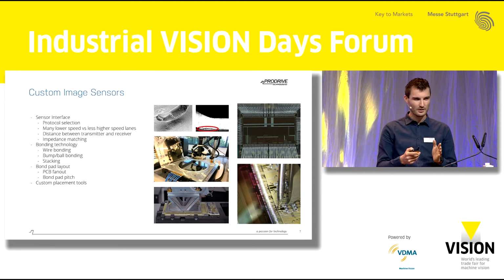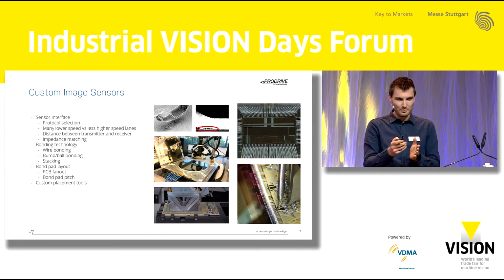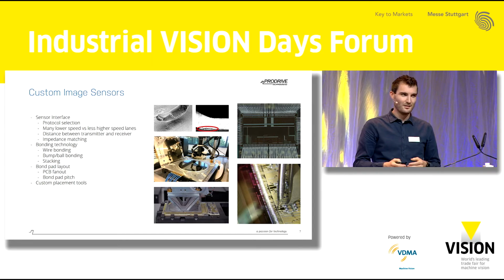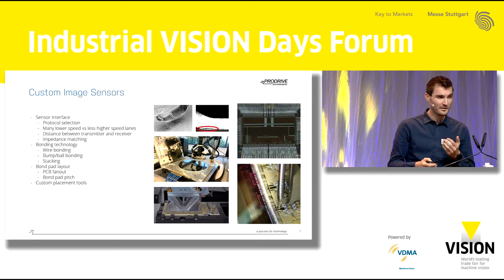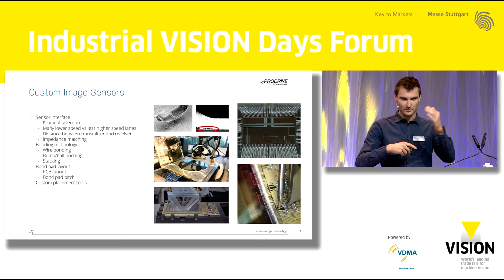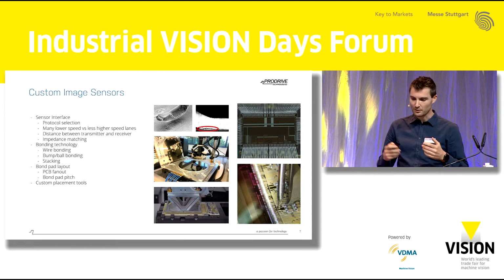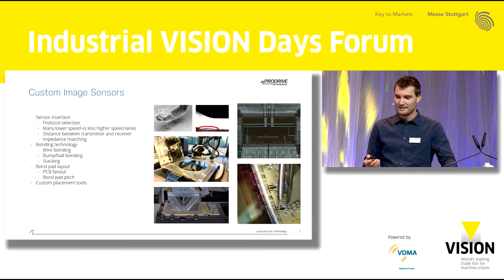An imager can't be too big. And then you have a certain bond pad pitch to think about. Creating multiple rows, or going for bump or ball bonding to have a 2D way to connect it. These are all things to think about when developing such an advanced camera system.